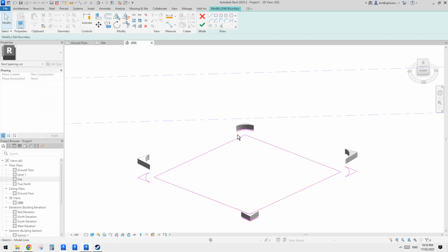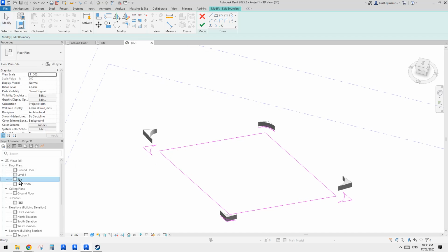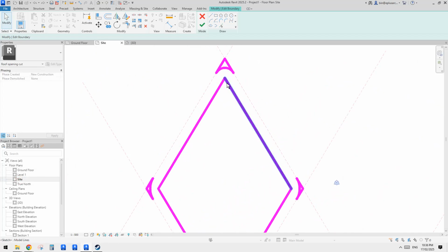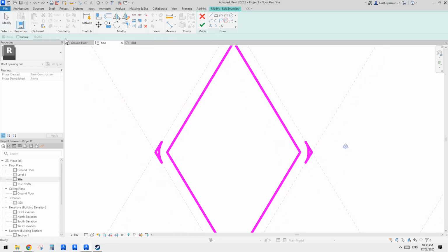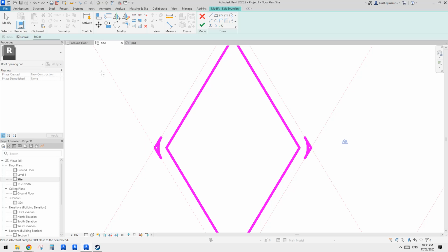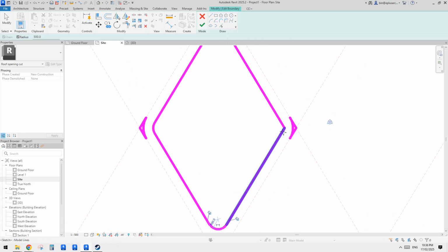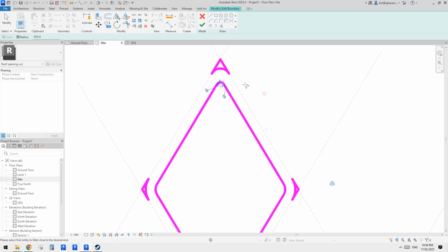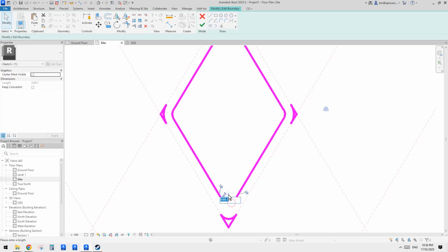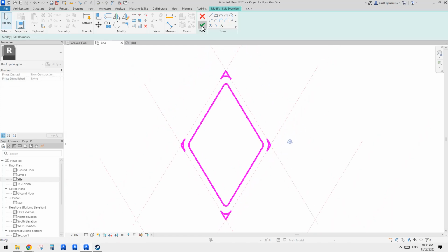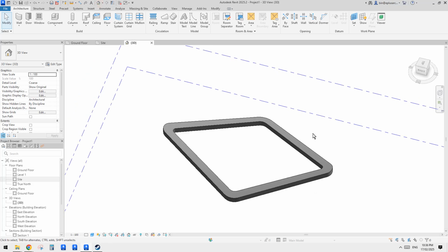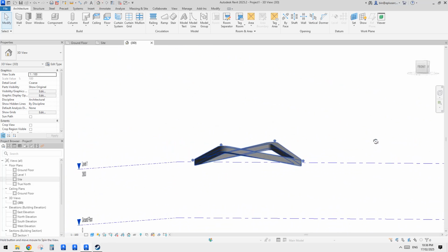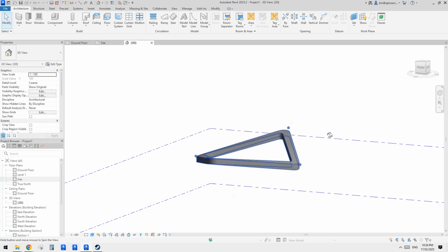Let's Control Z again. Go back to edit the sketch, go to the site plan. This time, I'm not sure what the radius needs to be, so maybe I'll just do 500 for all of them. Use a fillet arc, 500, 500, 500, and 500. It might look too big, so you can just change it to maybe 100 or 200, right? 200. So this is it. Now finish this. Now we have this perfect curved roof with the opening in the middle.